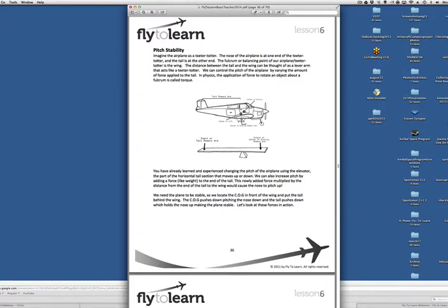All right. So you have tail moment arm balancing, and the fulcrum is that center of lift. It's not the center of gravity. What's the tail moment arm? Well, that's the distance from the center of lift back to the forces on the tail. On your Cessna 172, you can see the vectors are going in the opposite direction. On the front of it, it's the center of gravity moment arm, and it's just slightly in front of it, just a matter of inches.